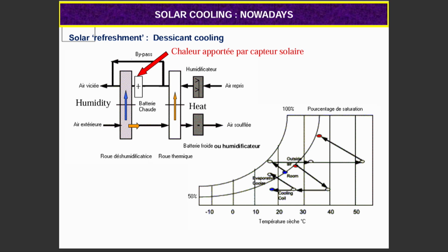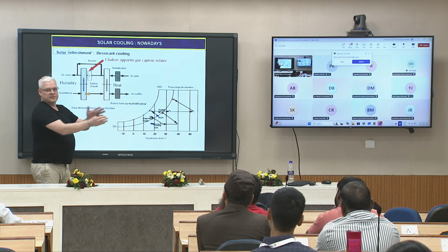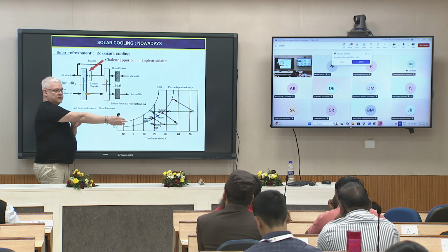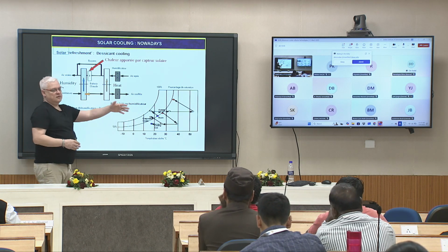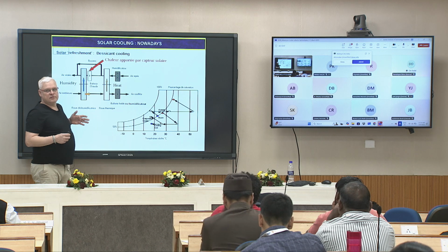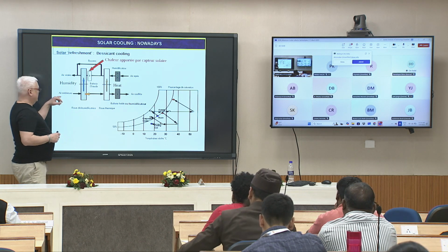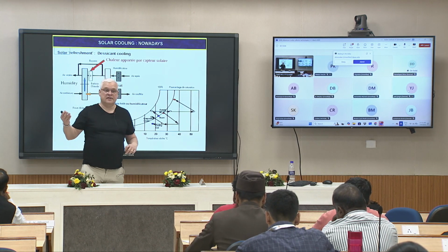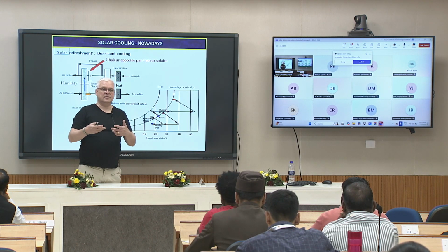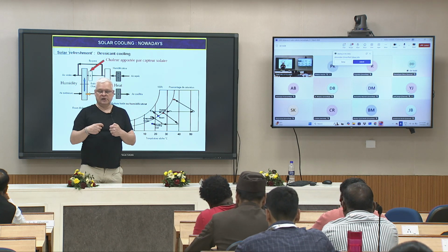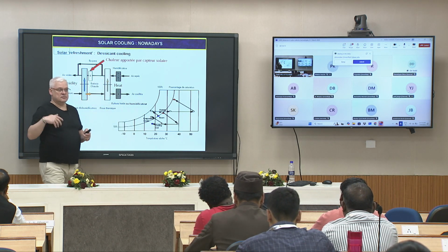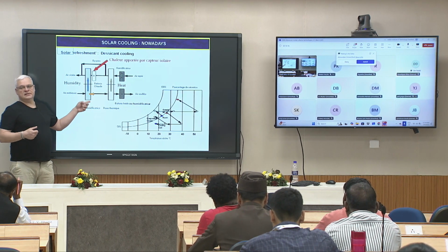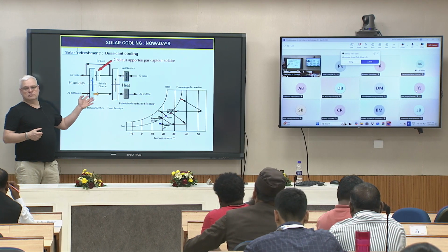You have a double flux management of air mechanically. You manage the injection of fresh air in the building, and you manage the exhaust of air. As I told you, if we want to humidify the air by evaporative cooling, first we have to dry it. So before the air is going inside the building, it is crossing what we call a desiccant wheel.